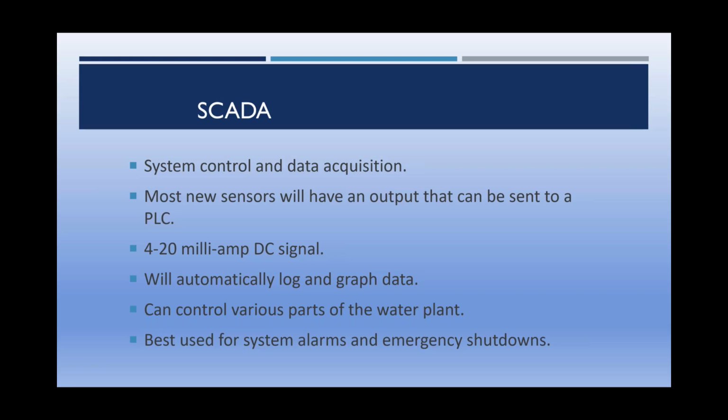I worked on a system where all the data collection points were fine. The pressure sensors, the flow meters, the pump hour meters, all these things were working fine, and they all sent their signals to a PLC, which you could then read the information off what's basically a screen. It's called an HMI, a human machine interface, and the screen failed.